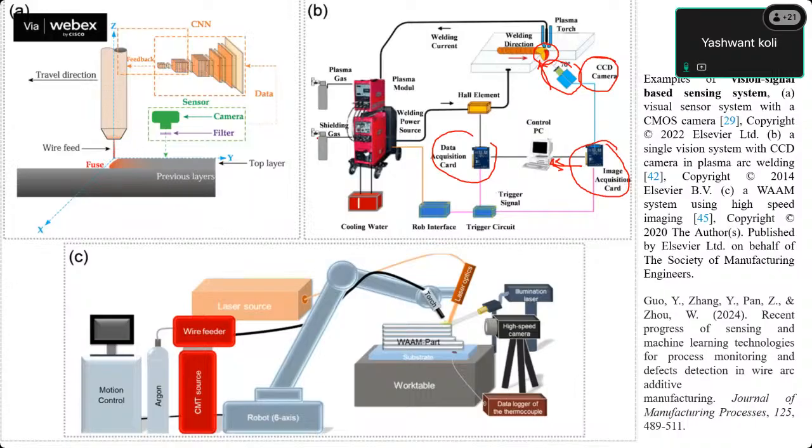Small defect detection is another: very tiny porosities can be overlooked because the accuracy and camera magnification is not that high if we are using normal CMOS CCD cameras. But if we take high resolution or highly magnified images, then we can detect the miniature porosity defects.